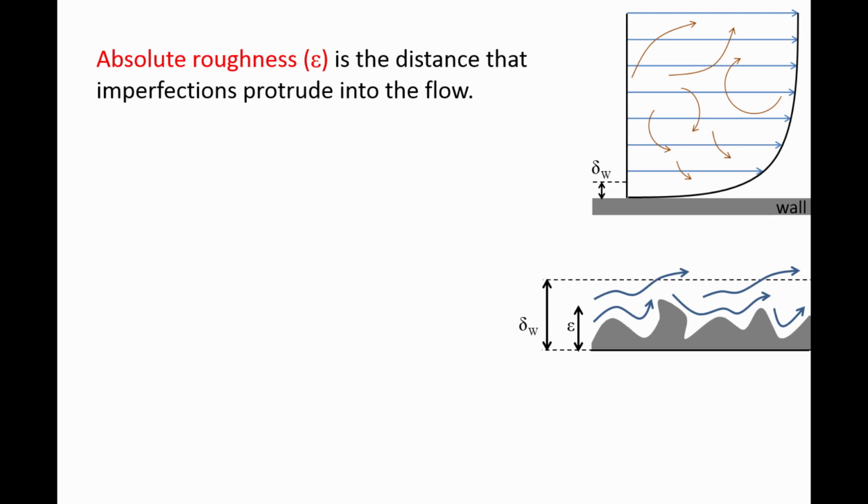The absolute roughness is usually quite small for new pipes and related to the pipe material. Very rough pipes, such as those made of concrete, have absolute roughness values that are typically tenths or hundredths of an inch in size. Some materials, such as glass and plastic, have negligible values for the absolute roughness, and pipes made of these materials are said to be hydraulically smooth.